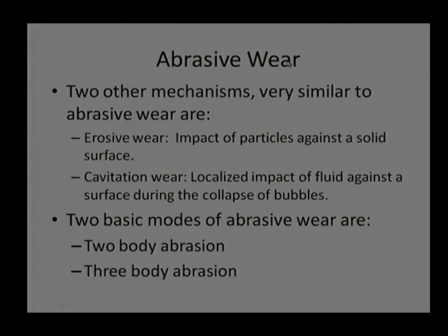Now, further we will come to the wear. We say that the basic modes of wear, abrasive wear, can be further classified based on whether they are asperity versus asperity or particle versus asperities. If asperity versus asperity interaction occurs, we call it two body abrasion. Where particle versus asperity interaction happens, we call it third body or three body abrasion, assuming the loose particle as a third body. We already have two surfaces, a soft surface and a harder surface, and there will be some particle in between. Naturally, a question arises: is two body abrasion bad or is three body abrasion bad? Which should be preferred?